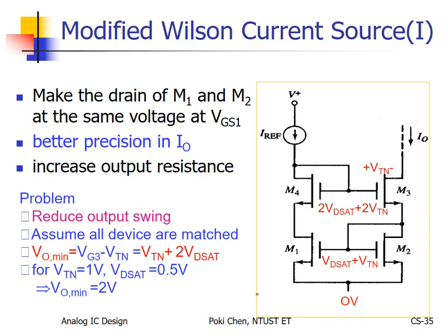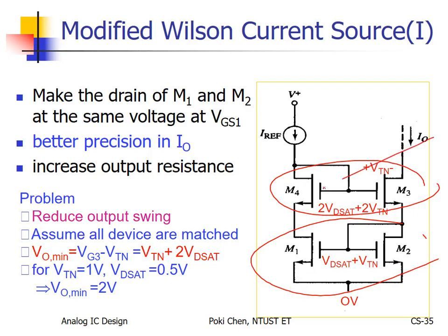You need to train yourself. All right, so which are important? M1 and M2. And as for M3 and M4, if you have time, you can match them. If you don't have time, you don't have chip area, right? If the chip area is not large enough, then forget about M3 and M4.